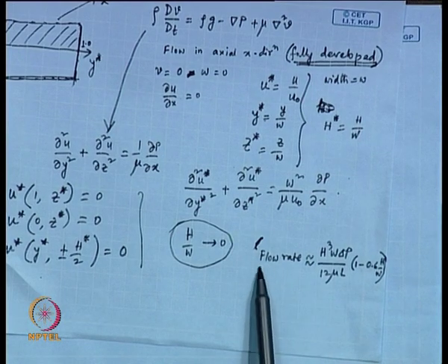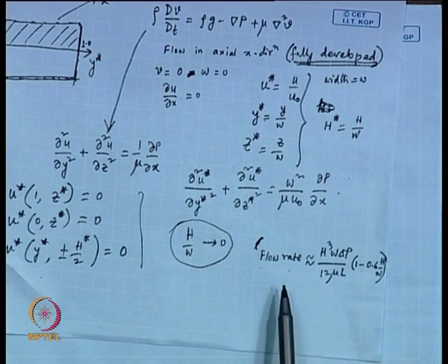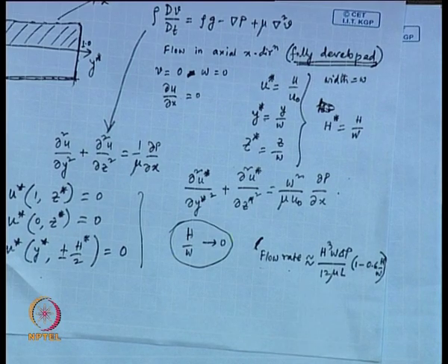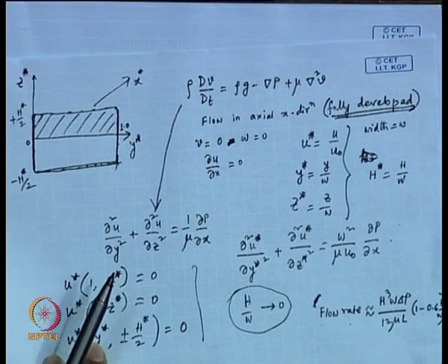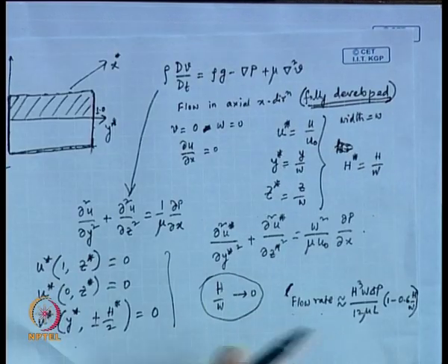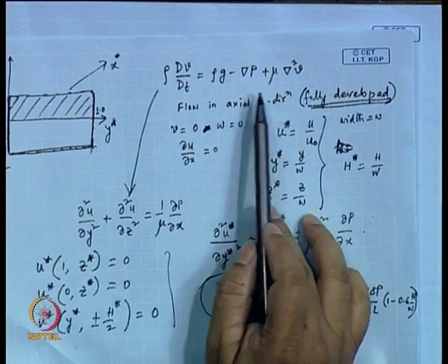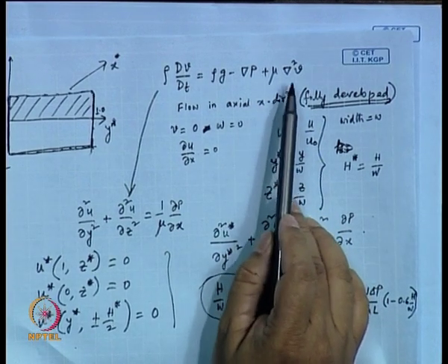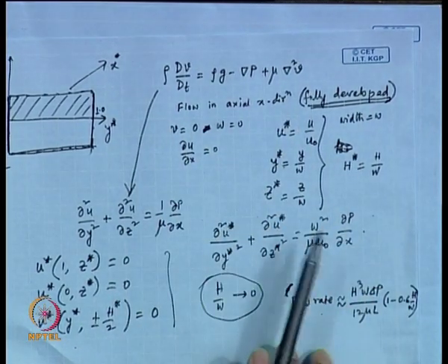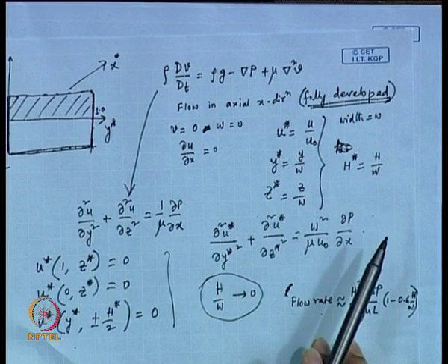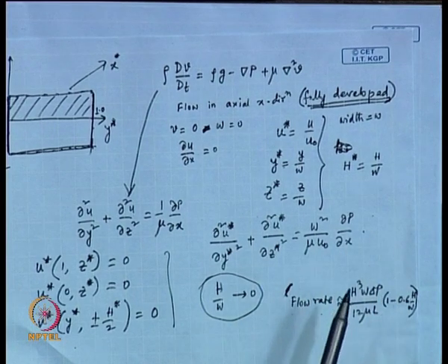So, if the flow rate is known, you can find out what the pressure drop is for a non-circular channel. But I must point out, this is entirely for a Navier-Stokes equation for a non-circular channel. This is the equation, but there could be other considerations that would alter the whole scenario. If you want to get some idea quickly of how much pressure drop you can expect, if you use a no slip boundary condition and the Navier-Stokes equation is valid, then probably you can use these equations.